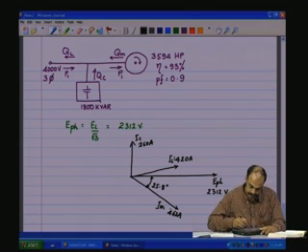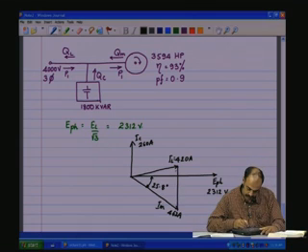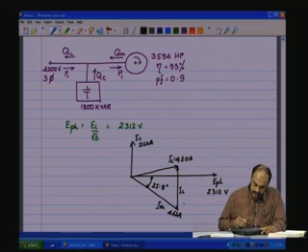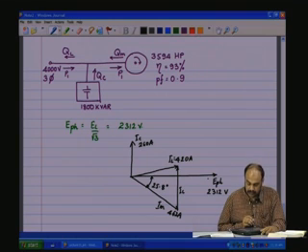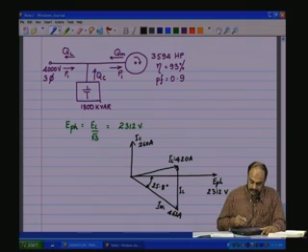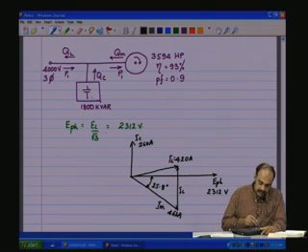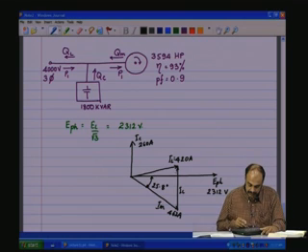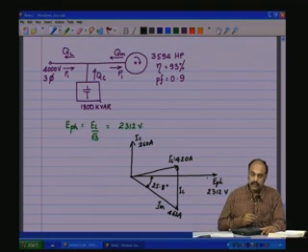So, IM plus IC will give you IL, and because of the reactive nature of IC, we see the improvement in the power factor as we discussed earlier, and that makes it in phase. So, if we adjust the value of IC by adjusting the values of the capacitive reactance, one could make it in phase.